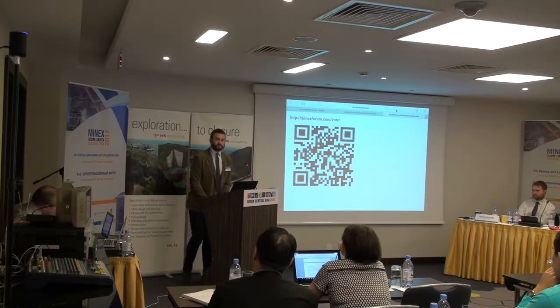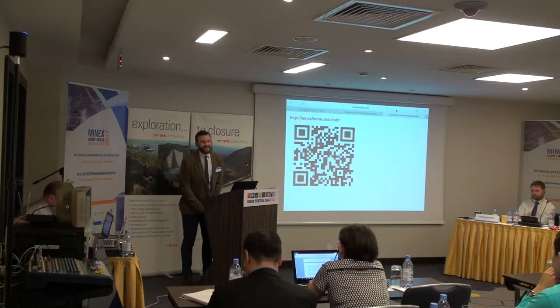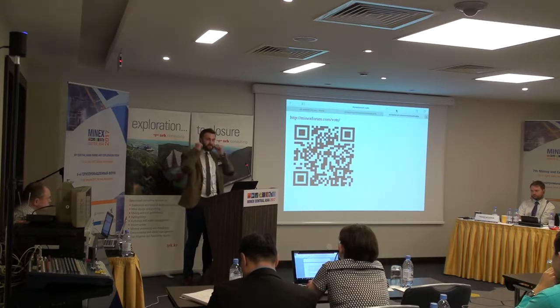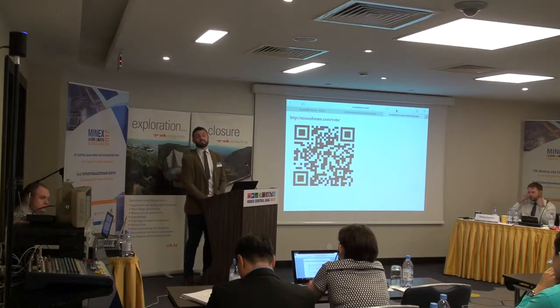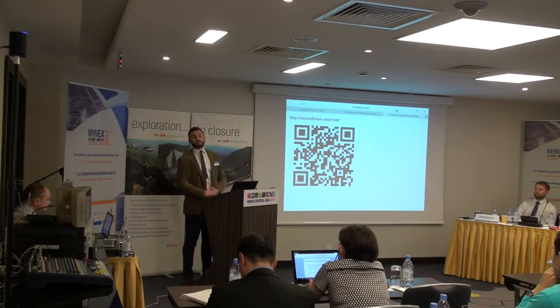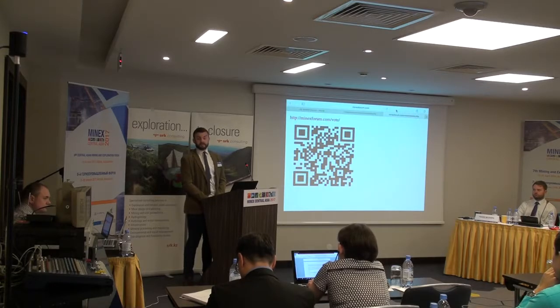Short answer, no. I haven't seen a specific rock mass model. What we try to do at the early stage of any project, at the proposal stage, is have a meeting between different disciplines to work out what the risks to the project are. For instance, you can tell very early on if it's a weak rock mass that's going to have high groundwater levels, then getting a good understanding of your groundwater conditions for that particular deposit is critical.